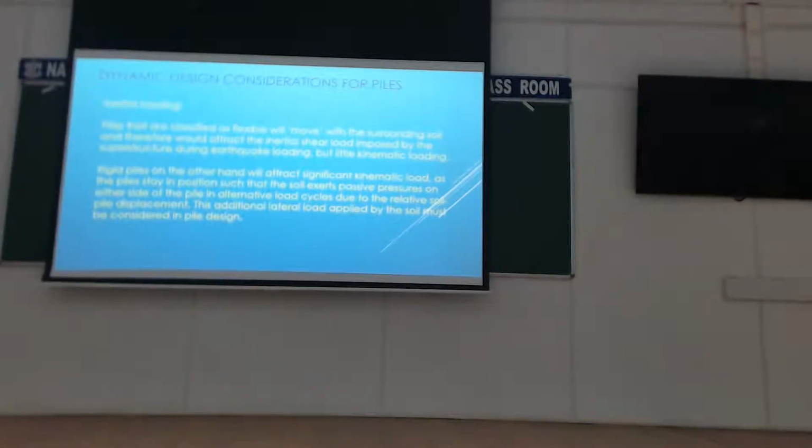So what we have done here is had a rough idea, quite foolishly and in ways I don't approve of. We worked out whether piles can be flexible or rigid, roughly. And at least that gives us an inkling of whether we should worry about the kinematic load or whether we should worry about the inertial loads. Okay?